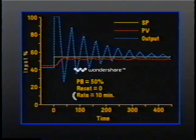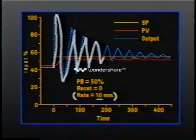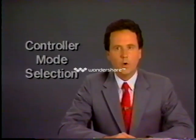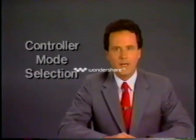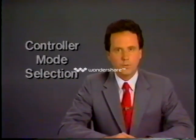Next, we increase the rate setting to 10 minutes, which has the effect of greatly increasing the total controller gain. Now we really get to see controller oscillations, and the process variable still won't come up to the new set point. From this, we can deduce that reset action will be necessary to bring the process variable to the desired level. Either fast processes with rapid changes in inputs or processes with signal noise that might appear to the controller to be an input change are poor candidates for derivative control.